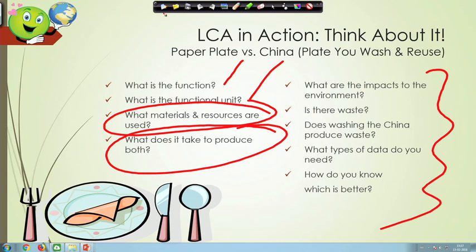Before we do that, let us look at what we do once we have this LCA information. We will collect all these environmental data, all these inventory data, we got the emissions numbers, but then what? After collecting this information, emissions in terms of solid waste, what is present in solid waste, what is the BOD number, COD numbers, or if they have benzene, arsenic, lead, or other heavy metals, or organics in terms of air pollution: SOx, NOx, particulate matter.